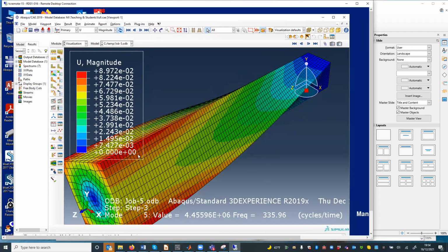And here you have this torsional mode. You can see the torsion of the beam. This torsional mode, you will not have it for the simple 2D model, okay? So that means that the fifth mode here will not correspond to the fifth mode of the simple 2D model.